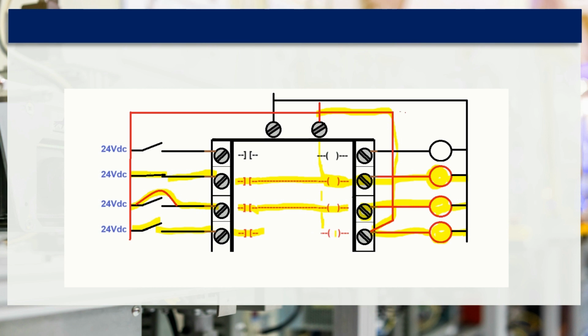Therefore, the output in our program is not turned on, but we've locked it on, and only the physical output is energized. Any associated contacts with that output will still be low in the logic. It's important to grasp that concept when it comes to forcing and locking on bits.